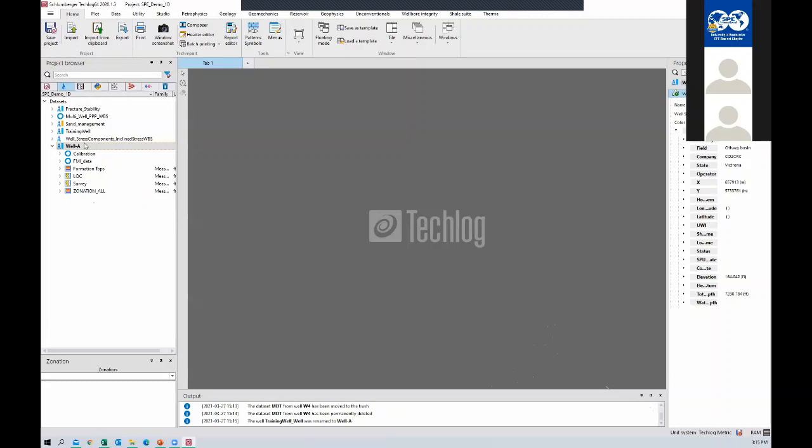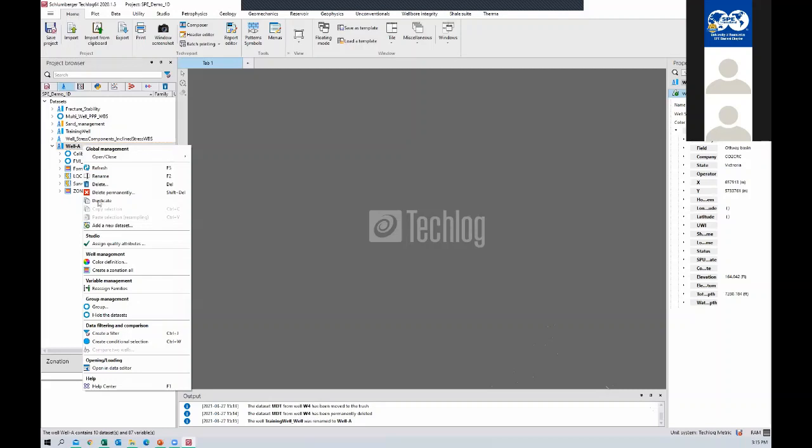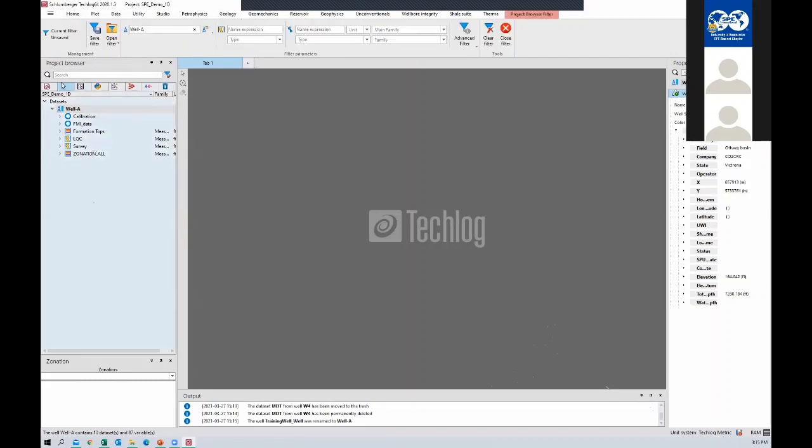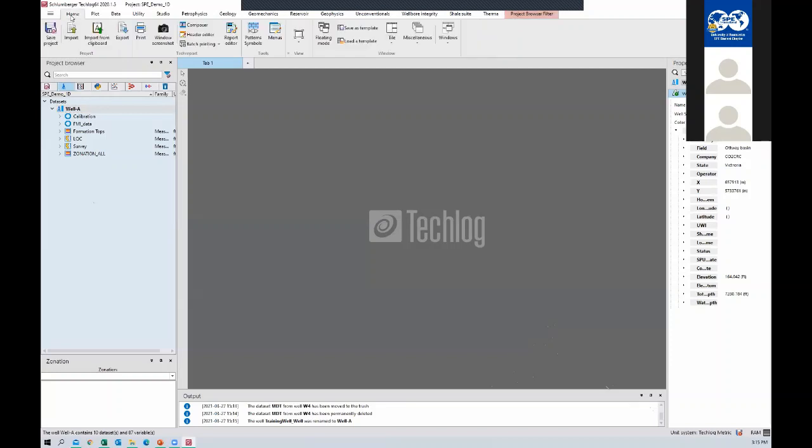Well A. Training well underscore well was a little confusing. And I don't want to see all the other things. I want to filter it out. What you can do is, again, right click. You can see there is an option to create a filter. The shortcut is Control J. So I will press Control J on my system. You can see other wells are gone. They are there in the project, but not visible. And I don't want to see them as of now, because it might be extra confusing. I don't want you to get confused with so many data sets.